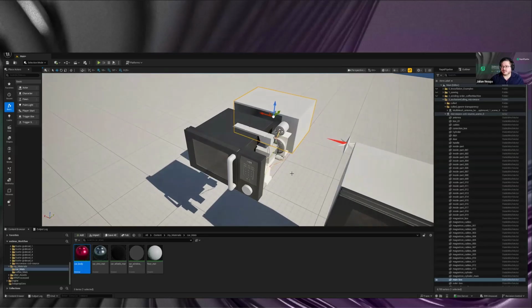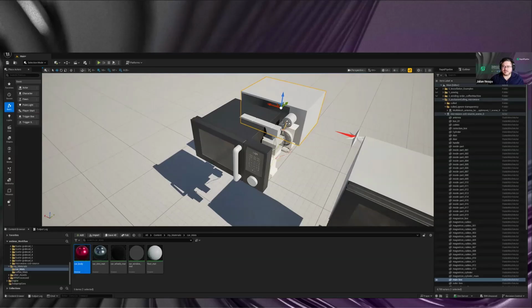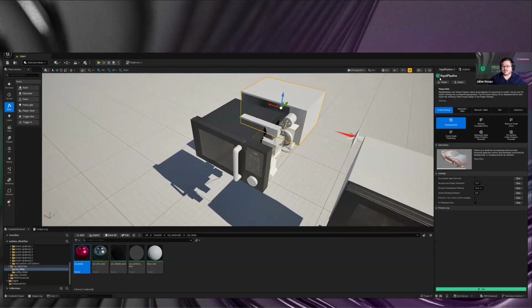If I'm not mistaken, there's a feature which Unreal does not natively have, and other 3D optimization solutions have it in a different way, where you have to set a volume first, or a camera distance and things. For Rapid, none of this is needed. It's again raycast based, and similar to the winding order correction, you have the option to do it per triangle or per mesh lump. You have a few more settings exposed in our occlusion culling action, which is called remove occluded parts, and you basically have a culling quality.